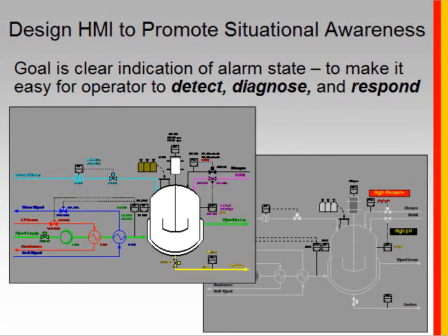We can see a couple of the alarm management HMI design recommendations demonstrated by these two graphics. First, colors that you use for alarms should be reserved for alarms only. On the screen on the left, alarms are yellow, and there's also a piping line for fluid that's yellow. That's going to be very confusing. We want the situation to be set up like it is on the right, where we're using dedicated reserved colors for alarms, and when you see that color, that's all it means.